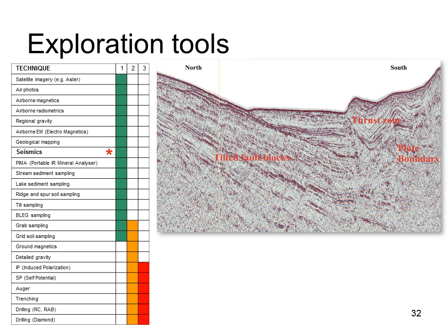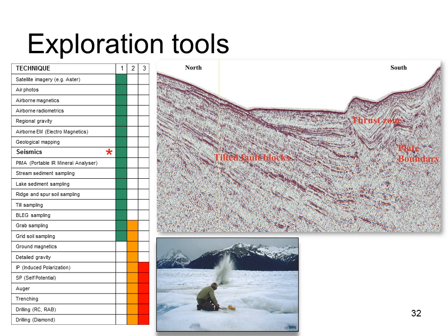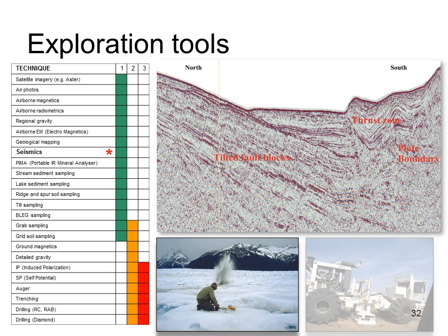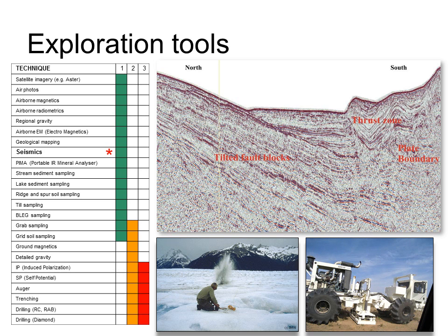Seismic surveys detect variations in seismic velocities in the Earth's crust, and so only work where there's inhomogeneous stratigraphy. The principle is to produce shock waves at the surface and then measure the echo as the waves are reflected or refracted off rock boundaries at depth. The initial shock waves are created by explosives or vibration using big trucks that repeatedly drop weights or simply vibrate large pads in contact with the ground.